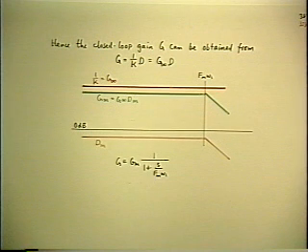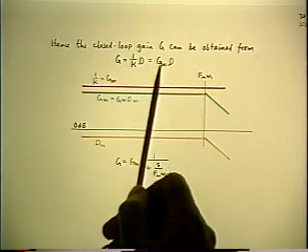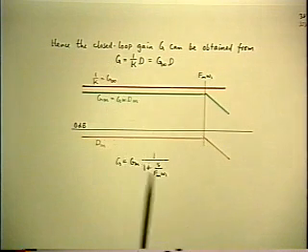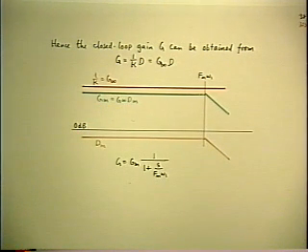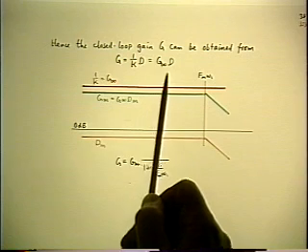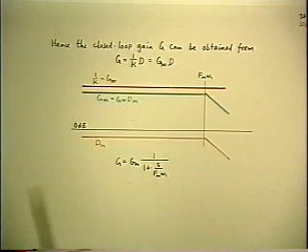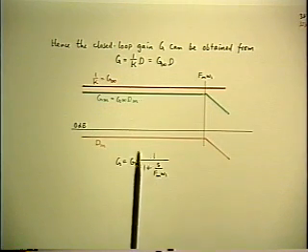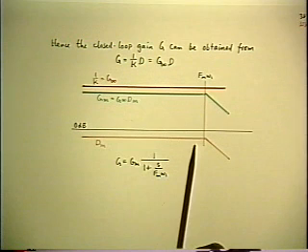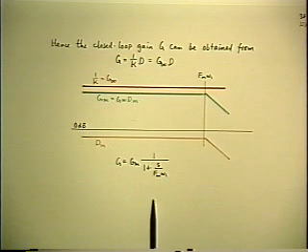Now, this is the end of the analysis, because we now have identified the midband values and the frequency response of all of the quantities that determine the closed loop gain of the system. And the G infinity we knew to begin with, because that's the specification, and all we started with was the T. I've assumed that we've analyzed for the T. A little later on we'll see how you do that. But having found the T, this is how you pursue the result to the answer. And there's no algebra, simply graphical constructions.